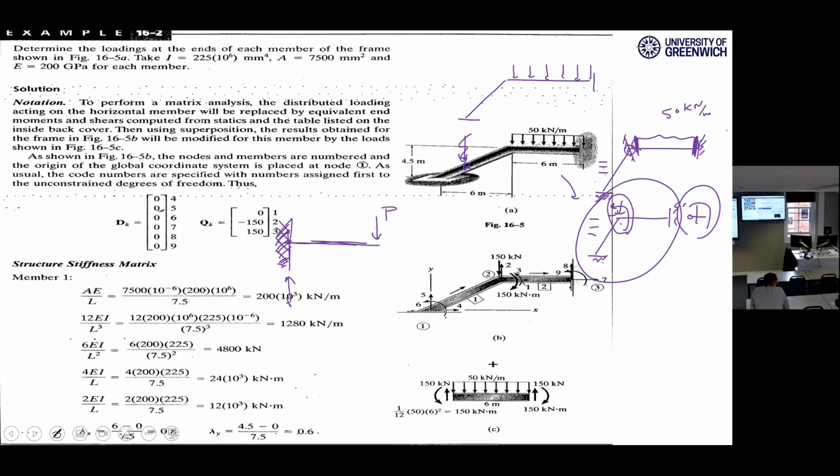You just have a support reaction locally there. It pushes back on you. It's Newton's law. Nothing happens. This is not from the P, I'm pushing the support. If you push the support like this, does anything happen in the beam? No. Something happens in the beam if you have some loading on the beam, like P. P can make some deformation on your beam. But this cannot do anything on your beam.